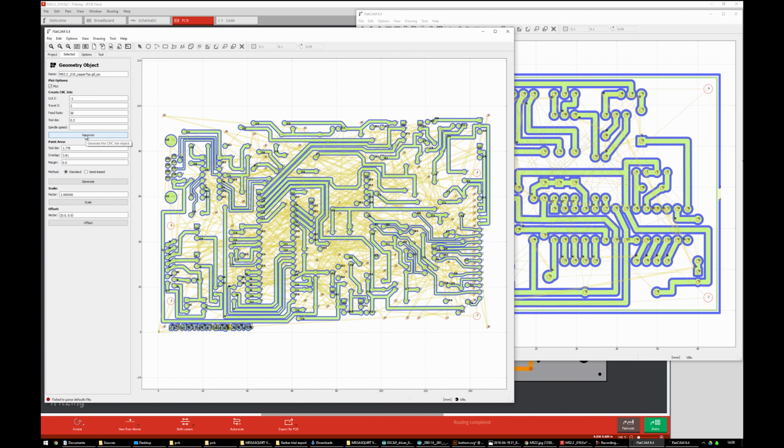One thing to note is that the blue G-code will obviously follow the ISO, which is that thin red line, or dark line, that it's just generated. It's very thin, I can't really tell what color it is. So the G-code follows that. When you click generate, no extra toolpath is generated. It basically just follows that ISO.